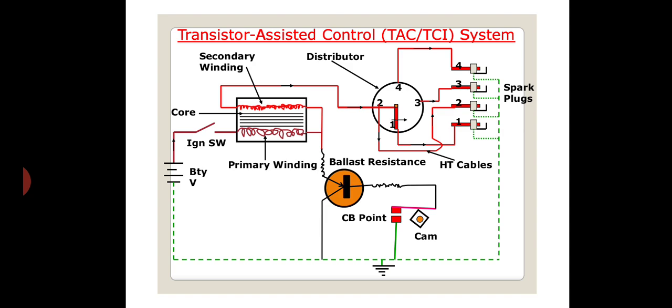The control module contains a timing circuit, which later closes the primary circuit so that the build-up of primary current can occur for the next cycle. There are many types of pulse generator that can trigger the electronic circuit of the ignition system. A magnetic pulse generator, where a gear shaped iron rotor driven by the distributor shaft rotates past the pole of a stationary magnetic pickup, is generally used.